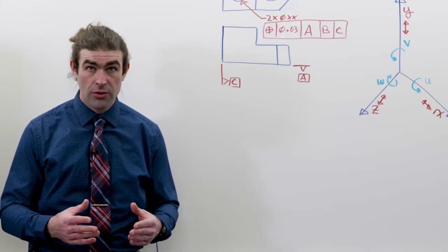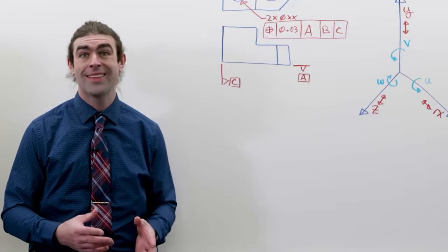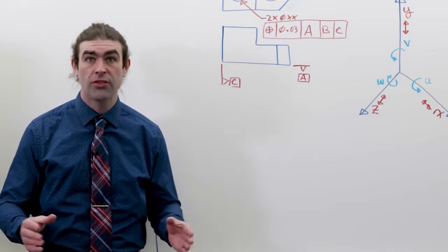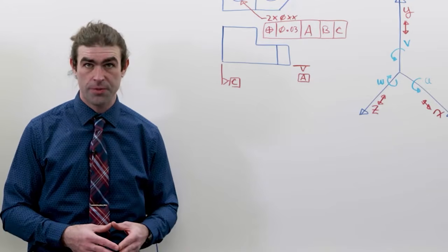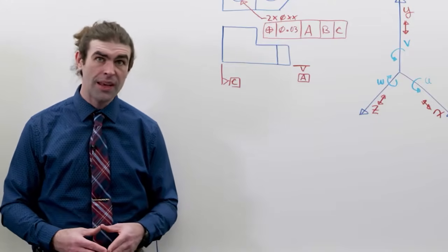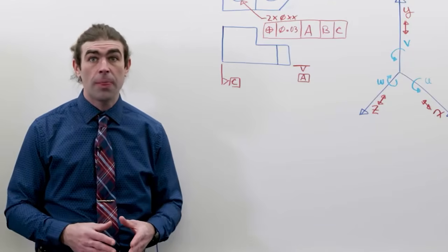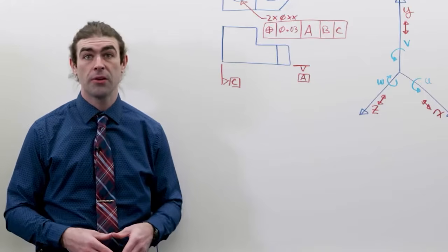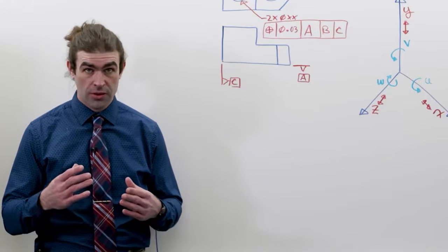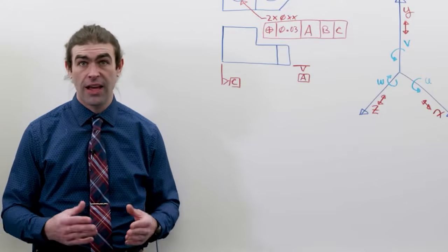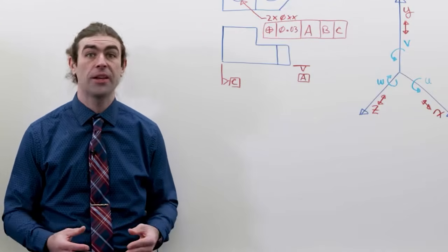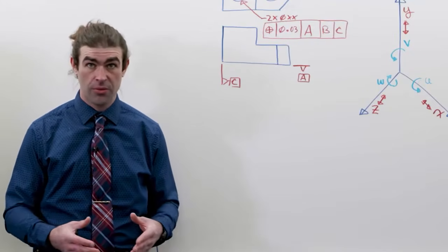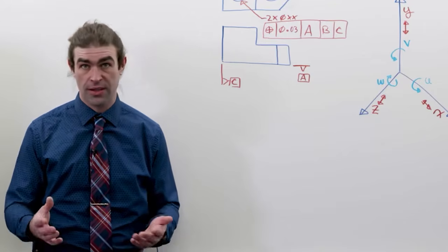So in the Cartesian coordinate system, you have X, Y, and Z. They're normally represented by lines going in totally opposite directions. They're 180 degrees from each other. They're 90 degrees from each other. Now, in GD&T, our datum reference frame is represented by 3 mutually perpendicular planes. Now, theoretically, they're perfect. They're exactly 90 degrees apart. In reality, they're not. And we'll at some point talk about how we square the circle with that, theoretical and what you can actually inspect.